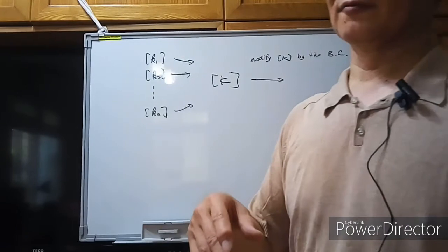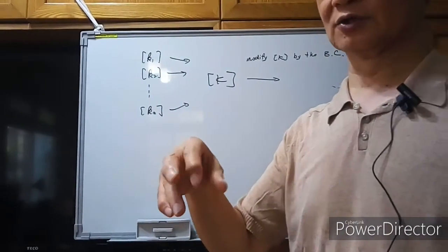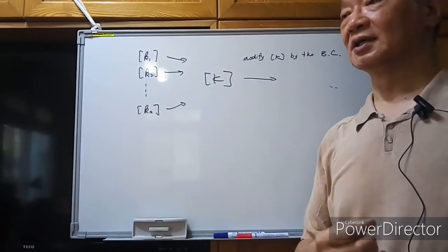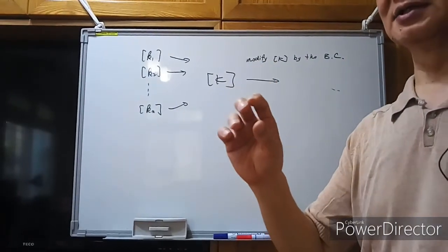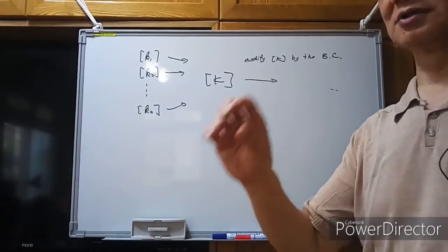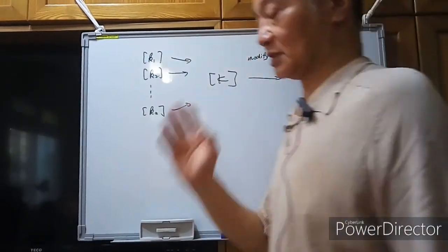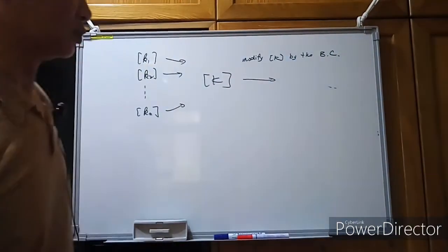For the MIT's method, we modify the off-diagonals to zeros and the diagonal element to be 1. And for the Berkeley's method, we just add very large numbers to the corresponding diagonal elements. Okay, so those are the methods we can use to consider the boundary conditions.